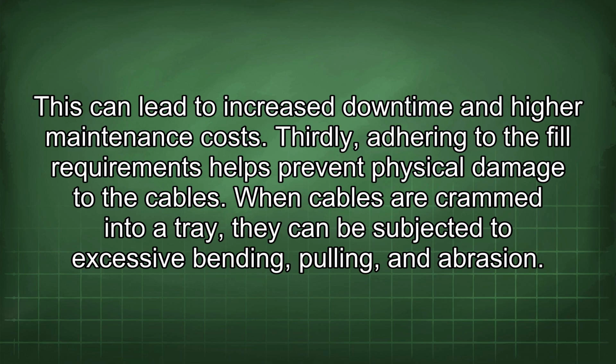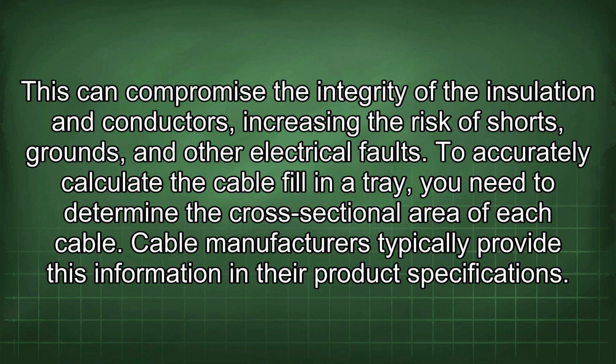Thirdly, adhering to the fill requirements helps prevent physical damage to the cables. When cables are crammed into a tray, they can be subjected to excessive bending, pulling, and abrasion. This can compromise the integrity of the insulation and conductors, increasing the risk of shorts, grounds, and other electrical faults.